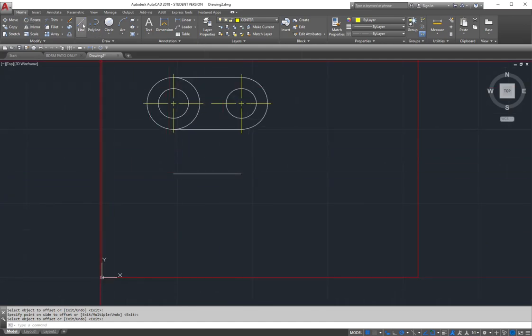If you recall, projecting multi-view drawings from the top to the front, I know this has to project somewhere right here. Now you can see something is going on right here that I shouldn't be doing. Hopefully you realize that. As you can see, these lines shouldn't be center lines. They should be under the object line.